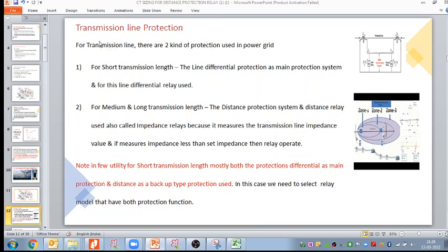Correct, correct. And one more point, let us add. Silpa also very correctly added one more point. Fault location is not an issue in a short line, because the line length is 5 kilometers, say 10 kilometers. In that case, the fault location point is not any concern. Any O&M engineer can easily go 5 kilometers and trace out where the fault has happened. So both points, as Raghunath said and as Silpa said, we can add.